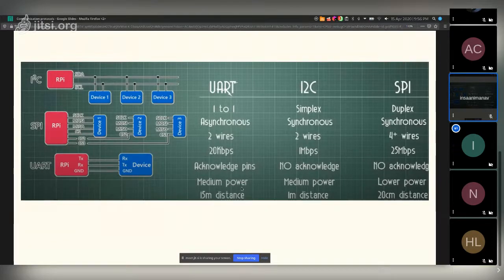received somewhere. Both of these consume medium power. SPI can run on both low and medium power situations. So if I have a certain use case, let's say a microcontroller is going to be mounted into a device that is going to be used for 30 days at a stretch, and I want to preserve the battery. Arduino and a lot of microcontrollers have sleep mode or low power mode built in. So SPI supports that mode and can actually work in this low power mode.